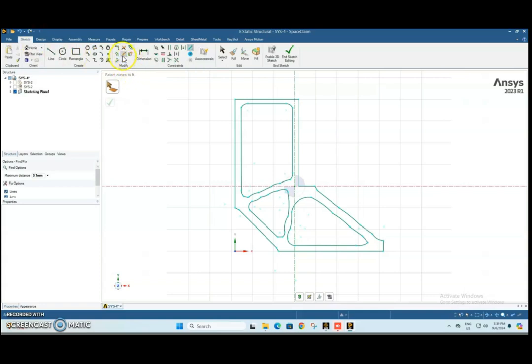Go to Sketch, and you have the so-called trim. You want to trim away all those curves that are not straight lines, and we replace them with a straight line. For example, you click trim, you trim this out, trim this out, trim this, then we can replace with a straight line, right? So it will be better like this. Continue with this one, which we also don't want. We can replace it with a straight line.